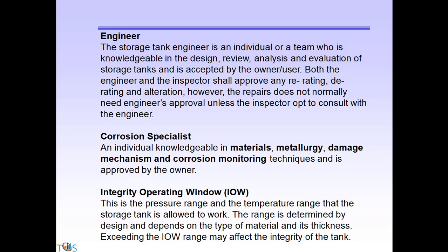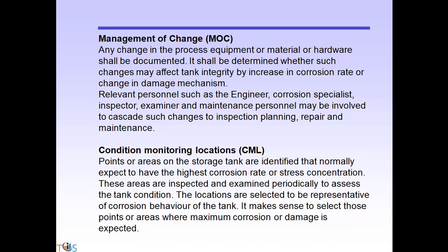Integrity operating window, IOW: the pressure and temperature range that the storage tank is allowed to work with the fluid. The range is determined by the design and depends on the type of material and its thickness. Exceeding the IOW range may affect the integrity of the tank.